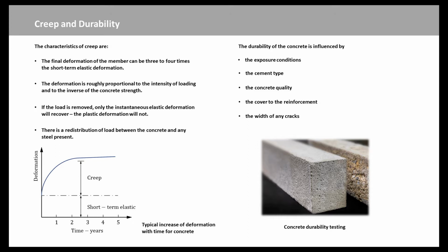Concrete can be exposed to a wide range of conditions such as the soil, seawater, the icing salts, stored chemicals, or the atmosphere. The severity of the exposure governs the type of concrete mix required and the minimum cover to the reinforcing steel. Whatever the exposure, the concrete mix should be made from impervious and chemically inert aggregates.